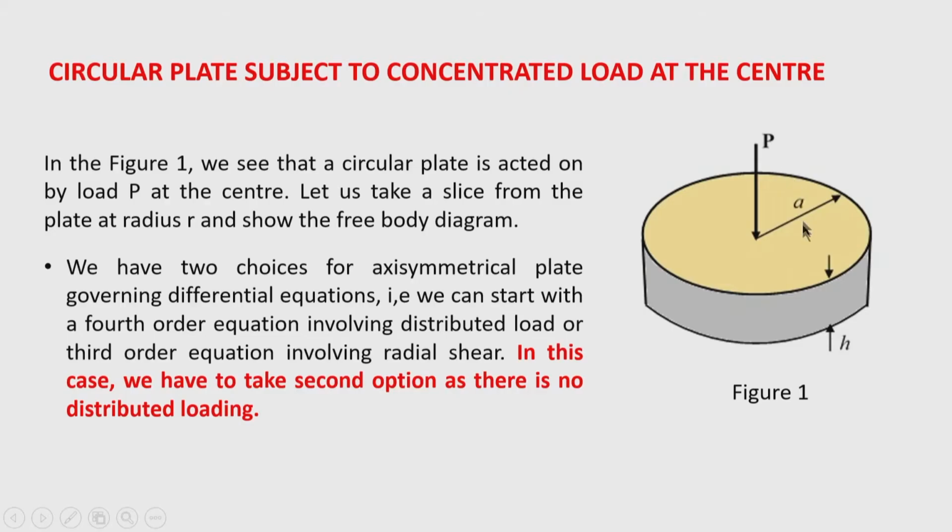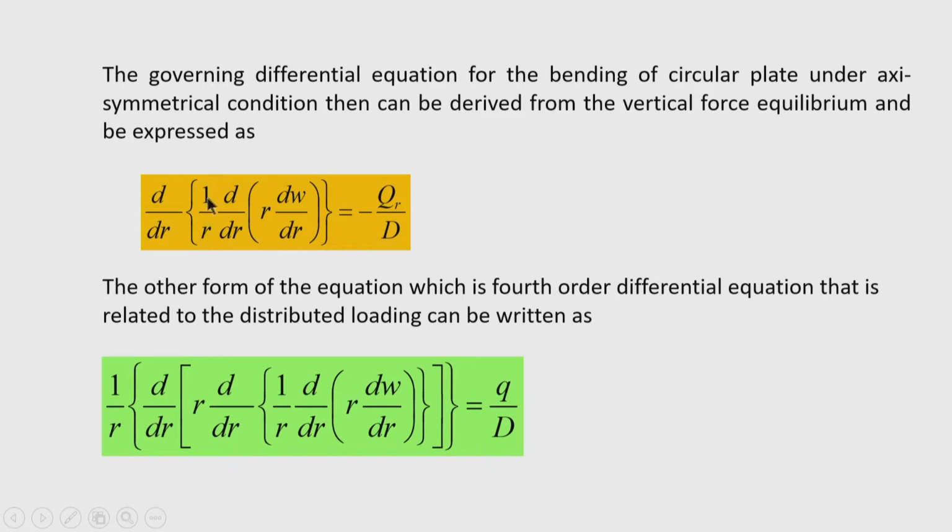Since there is no distributed load, the second option is better in this case, because in the absence of distributed load the forcing function of the differential equation cannot be written. So we take the second equation, which relates the third derivative of deflection with the shear force, with convenience. The other form cannot be used here because of the concentrated load action.